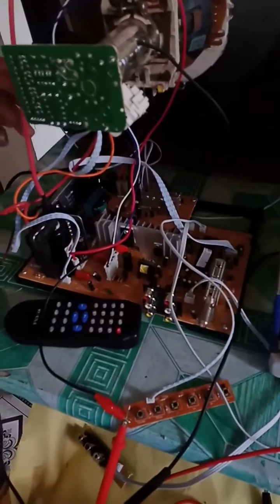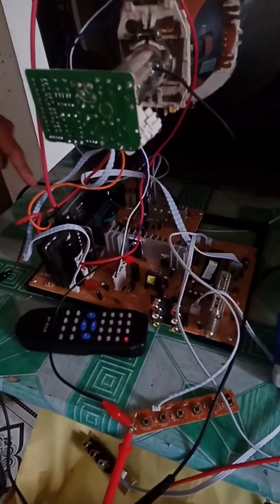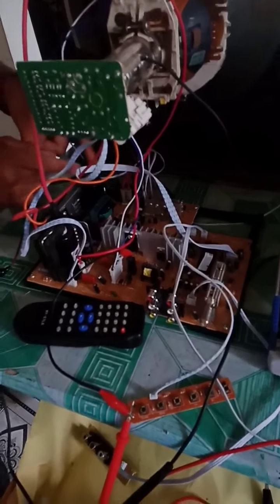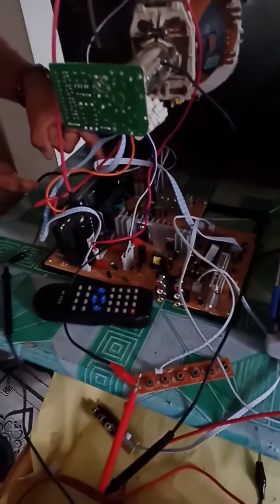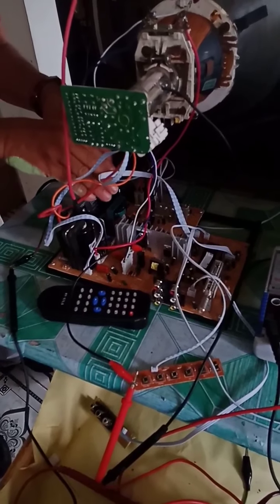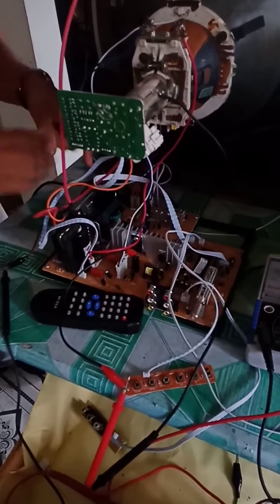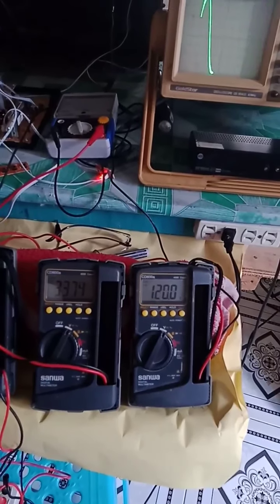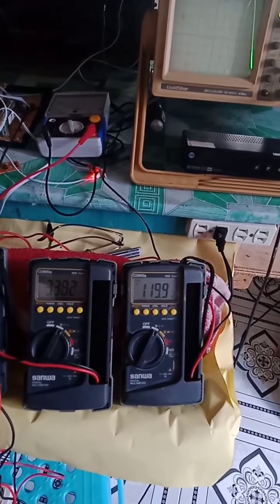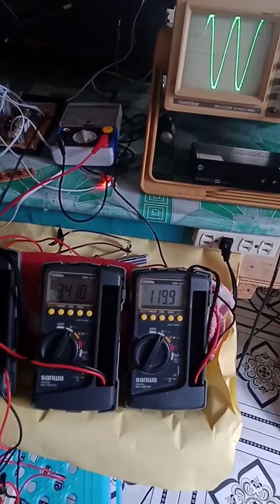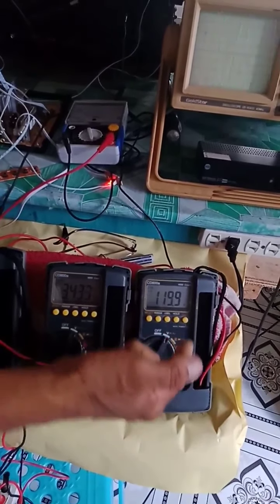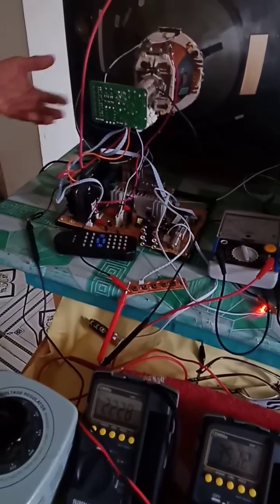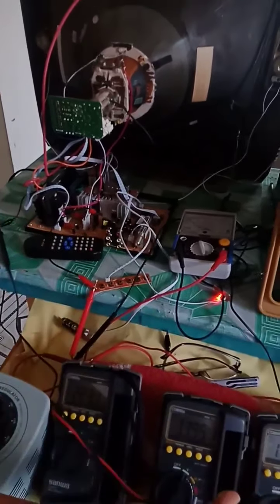Remember that this circuit here is a DC to DC converter, because what is being regulated is actually the DC voltage across this capacitor, which is the input voltage of this switch mode power supply, the regulator. It is lowered down to 119 volts or 120 volts. So 119.9 volts or 120 volts, that is actually the voltage at the output of the low voltage power supply, which is a regulated one.